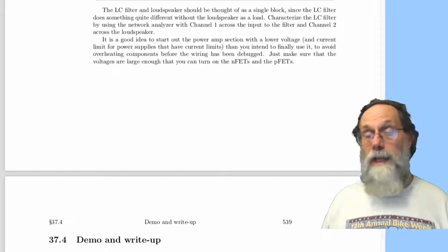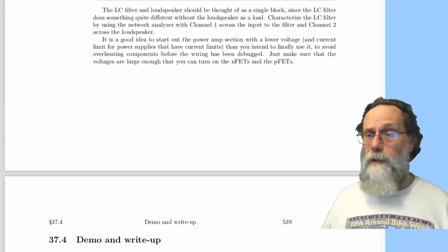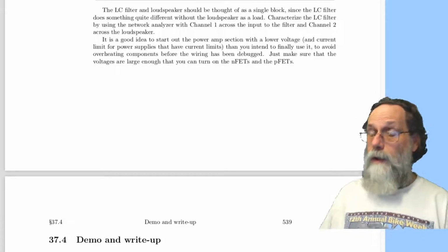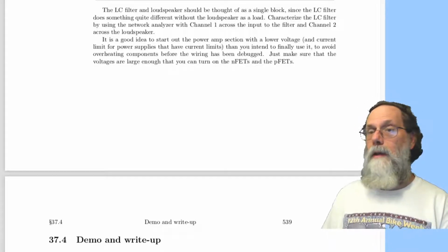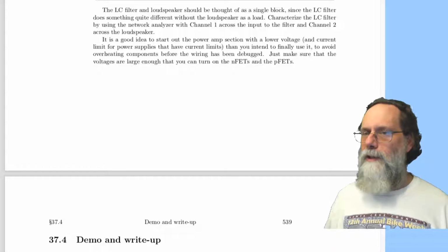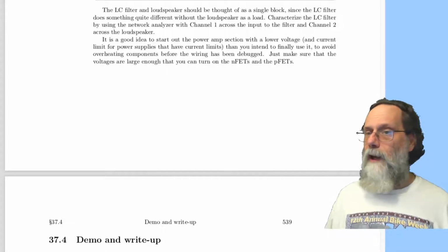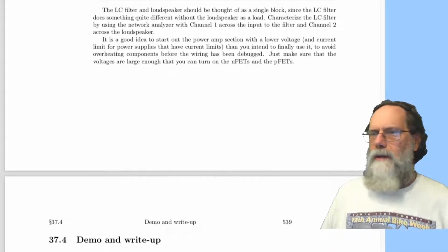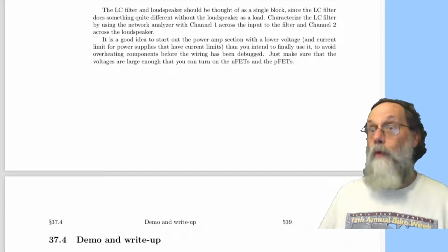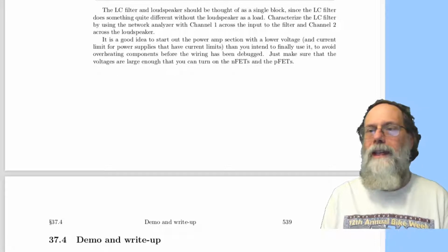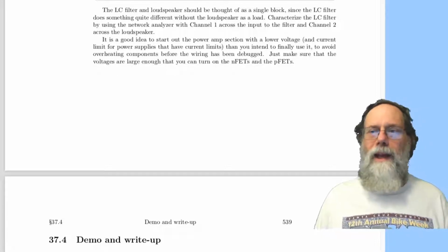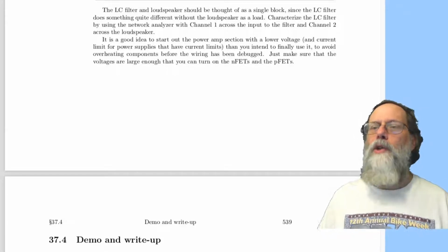And if you do it testing one step at a time, it's much easier to debug, because you can say, I know it's working up to this point, so just this one new thing I added must be where the problem is. If you try and build the whole thing all at once and it doesn't work, then it's really hard to figure out, well, why isn't it working? Is the whole thing wrong? Or is it just some wire missing, some misconnection? And it's very hard to debug if you've got a huge system to debug.